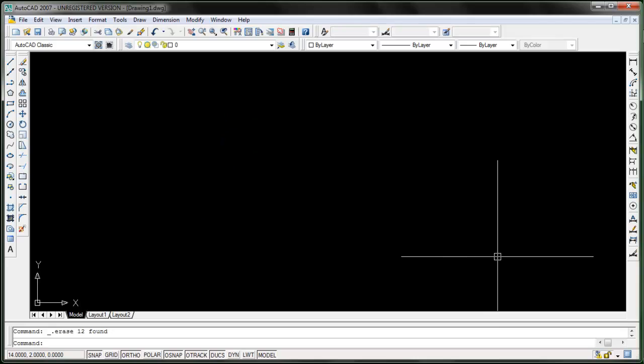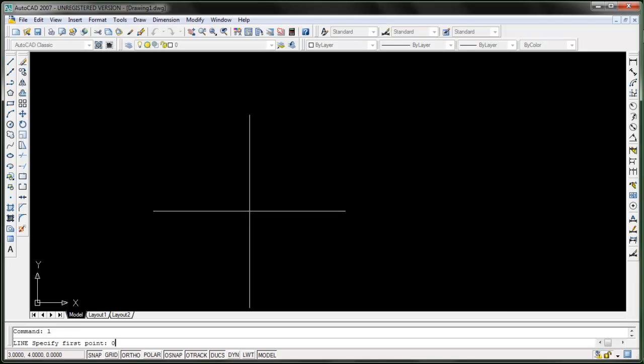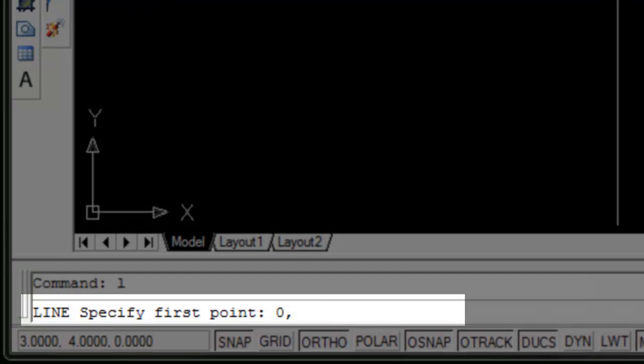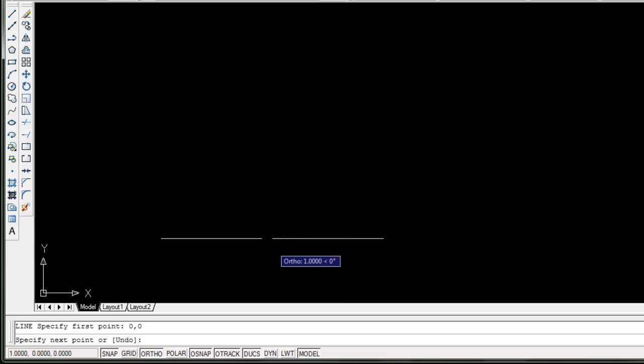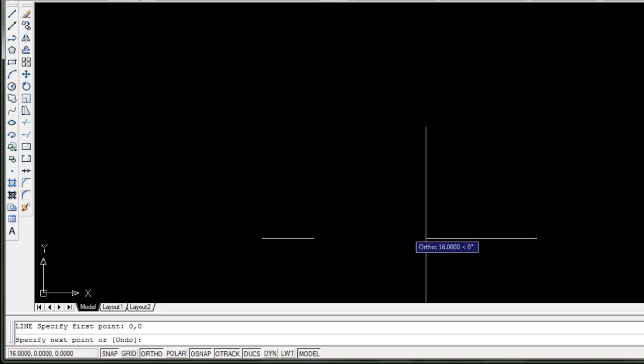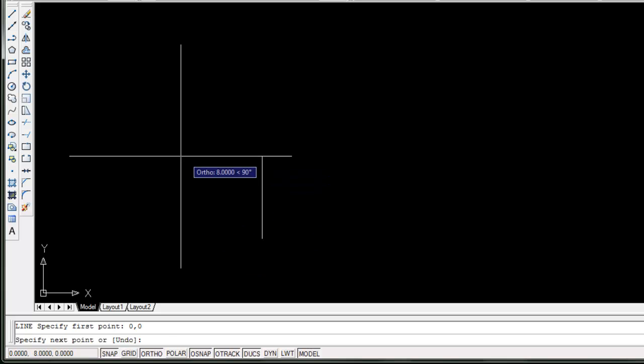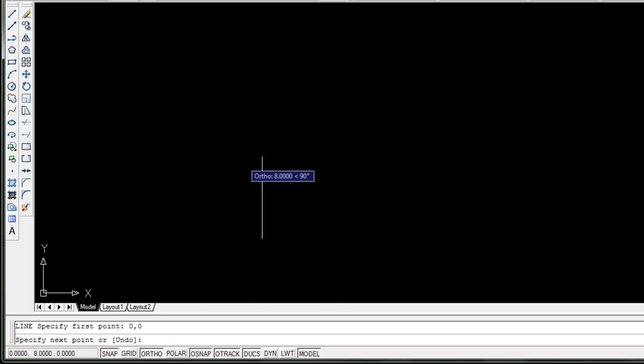This is the difference. Now I will show you about the coordinate system, the rectangular coordinate system and the polar coordinate system. If we want to find the 0 point of the workplace or our base in AutoCAD, how can we get that 0,0 point? To get the 0,0 point you have to write line, and then we'll write 0 comma 0, enter. We just got the 0,0 point, and from here we can go left, right, or anywhere.